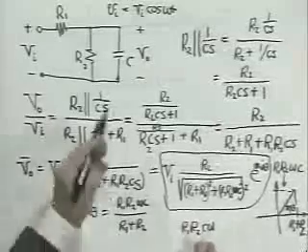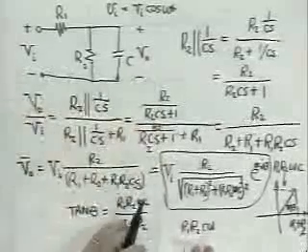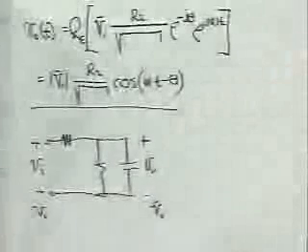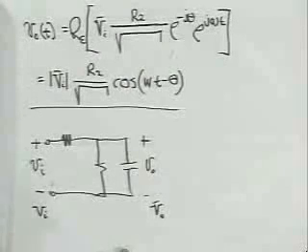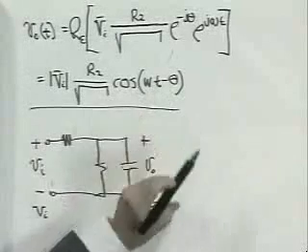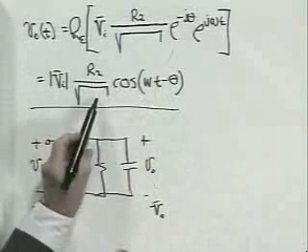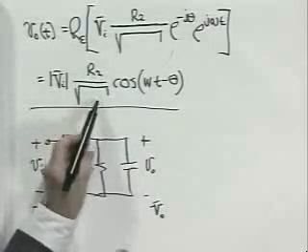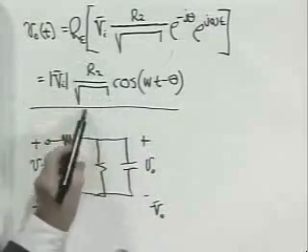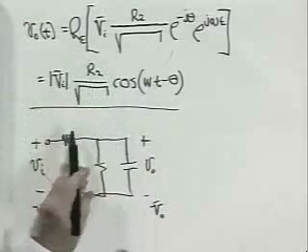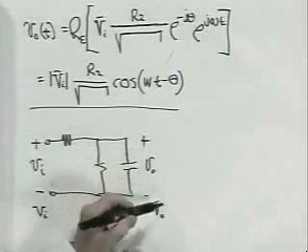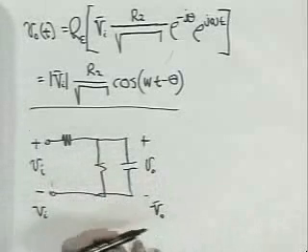So I just get the input voltage, cosine omega t, multiplied by the voltage division ratio. That makes sense. And if we go to larger and larger omegas, the very high omega, this angle approaches pi over 2. This relationship looks like a constant over omega because the R1, R2 omega C term in here dominates. So the whole amplitude factor goes down like 1 over omega and says that the voltage out here, the time function, gets smaller and smaller and smaller as I go to higher and higher frequencies.